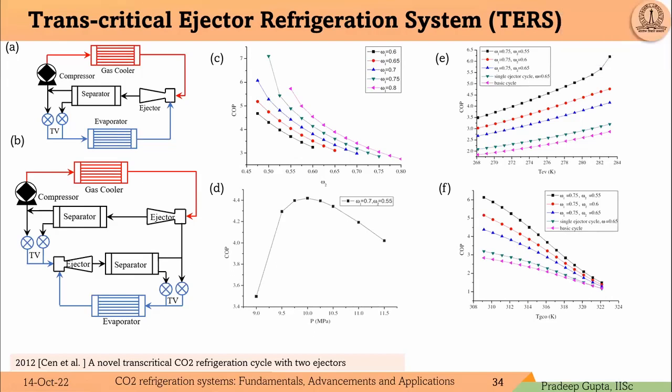So partly it is compressed, partly it is throttled. Here, just for the control issue, maybe 5% or 10% goes to the compressor and some to the throttle. We cannot say exactly how much it would be, but it's a very low number, because the entrainment ratio of this ejector and the dryness fraction at the end of the separator have a relation. To control that relation, we provided one extra throttle valve here.